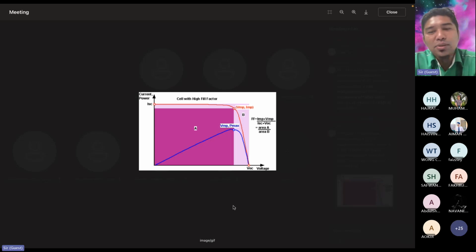Just to add on to the question, guys. Let's say we have a PV module, and the module states that the fill factor is 0.7. What can we say about the performance of the IV curve? Because from that equation, FF, the fill factor, is the ratio of the power based on IMP and VMP divided by the power from ISC and VOC. So anyone can share with the class, when we get 0.7 fill factor, what does it mean for our PV cell?